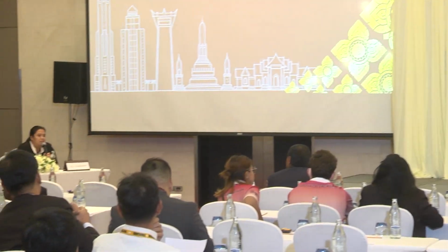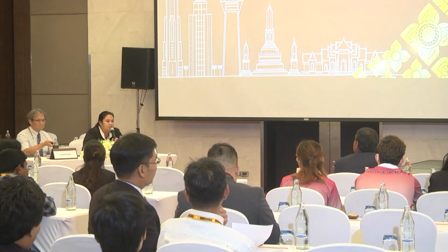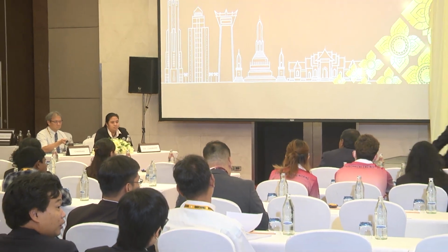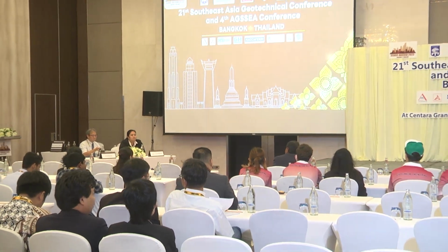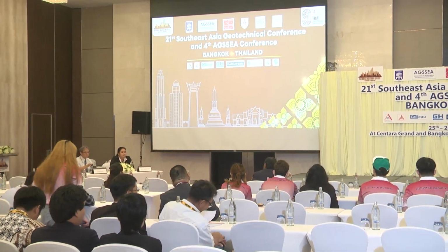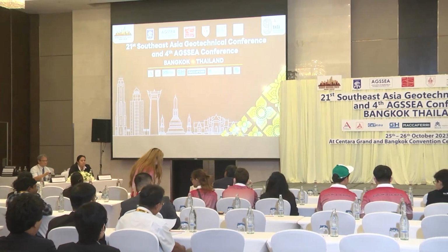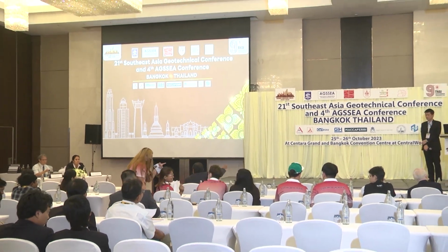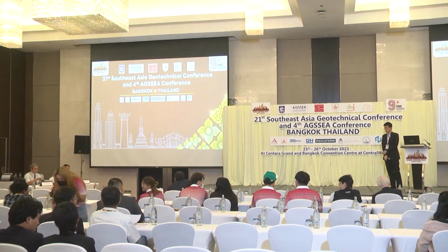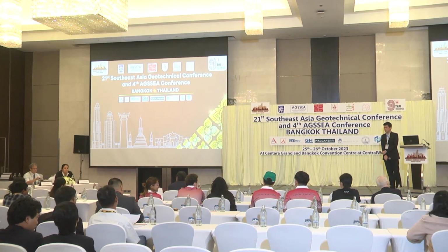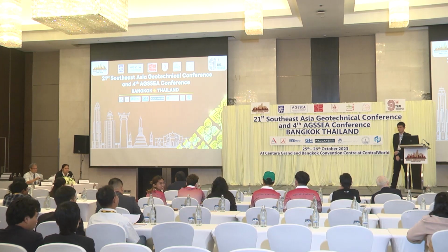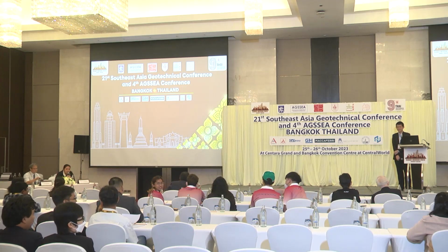Okay. Clay can be simulated in the discrete element model because natural clays exist as flocculated clay. They are not clayey anymore. Therefore, in the same way that you model sand particles, flocculated clay particles can be modeled with DEM with the contact forces that he actually put in his second slide. So it is possible to simulate clay behavior with DEM. Thank you, Professor.